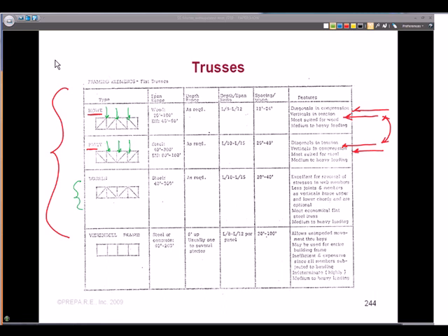And then we also have the Warren truss. And I would say the Howe truss and the Pratt truss, these are good for floor systems, okay? Versus the Warren truss, this is good for a roof system, primarily because it talks about stress reversal. It has diagonals going both directions that may be subjected to tension or compression. And shortly we'll be talking about what if there's a wind uplift on this roof, and we've talked about wind. Sometimes the load is pushing down, sometimes it's pulling up on this truss, so those diagonals have to be able to function both directions, okay?